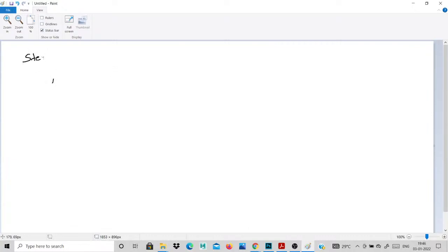Step 5 is the reinforcement calculations for your slabs. Take your moment value, then calculate the AST values for your buildings. This is the main important thing. You simply take this moment value, then calculate the AST, then you go for the reinforcement also.